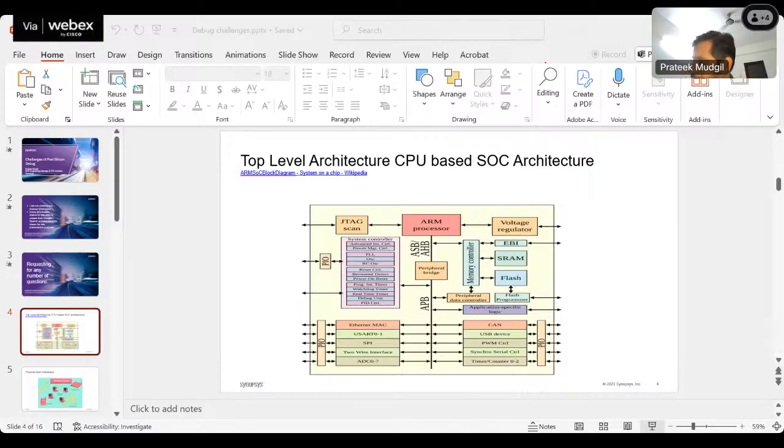And the second problem is that when the skew is deterministic, we call it synchronous. And when the skew is nondeterministic, we call it asynchronous, right? So there are techniques in physical layers. Let us say this clock is being sent here and data is being sent here. So there are analog blocks sitting here, which take the data and the clock, right? Initially real data doesn't come. Initially it tries to train itself. This block of the design is trying to understand what the trace length is, what the skew coming in is.